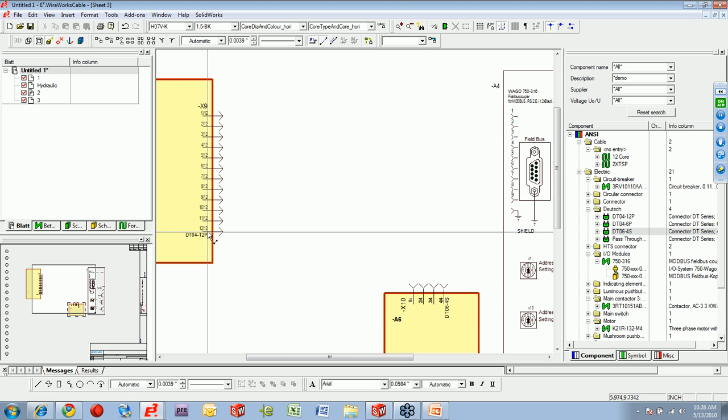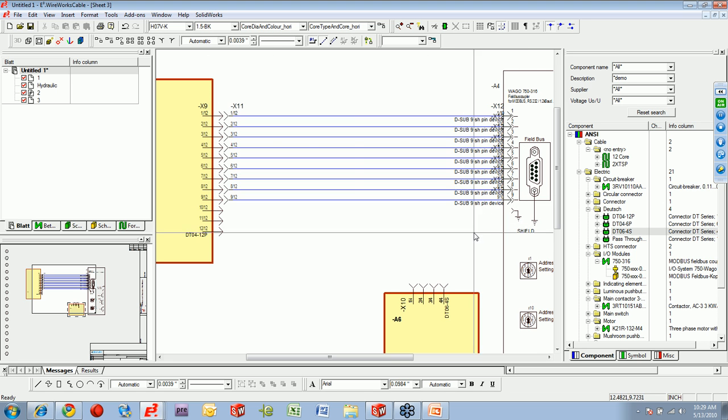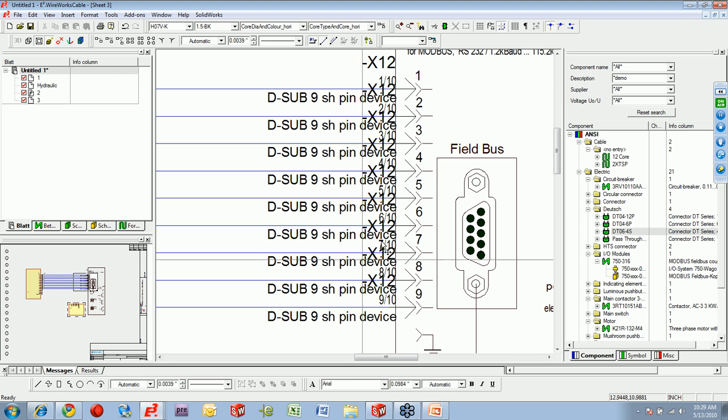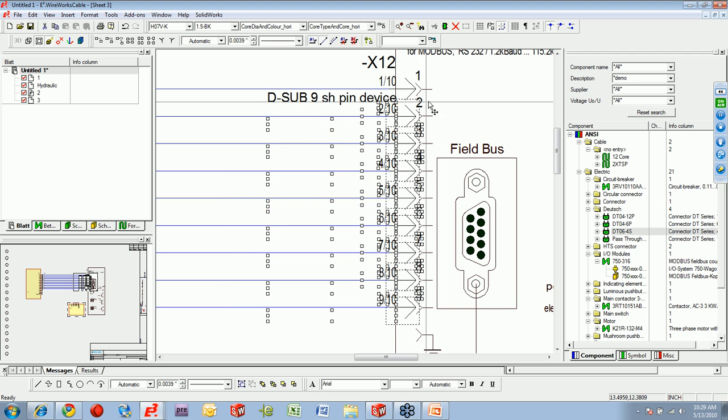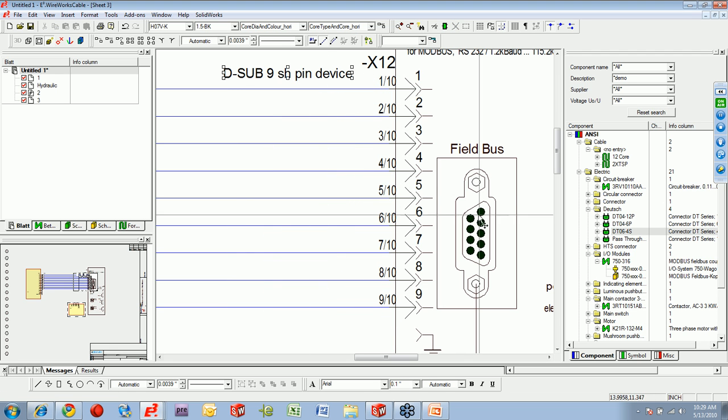And now we have a few receiving connectors in different systems, and we want to interconnect these systems. The same as before, we can use some quick connection. We can do like horizontal auto connect, where we can automatically put in all the pins, and it will put in the associated connectors. So it knows that this connection is the corresponding one to fit into the field bus.